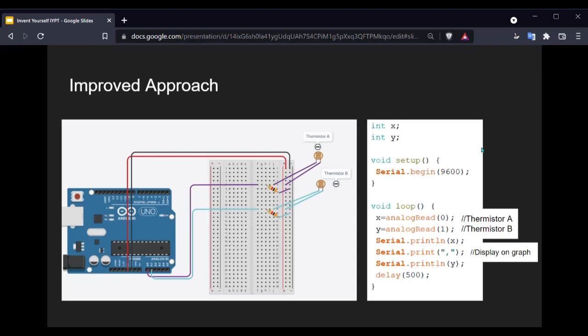This circuit displays a voltage divider using two series resistors, allowing each thermistor to display their respective values individually. When the temperature increases, the resistance decreases, meaning the voltage also increases. This is how we measure the temperature using the thermistors. With some code, the voltage of the two thermistors was able to be displayed in the form of a live graph, which we'll show you in a moment.